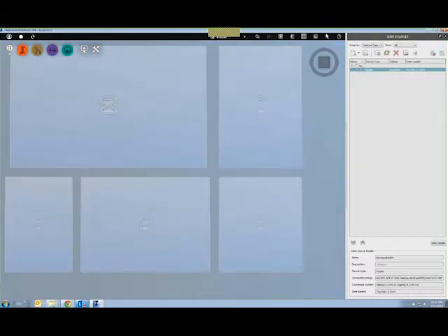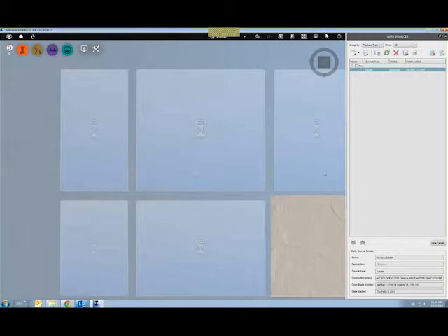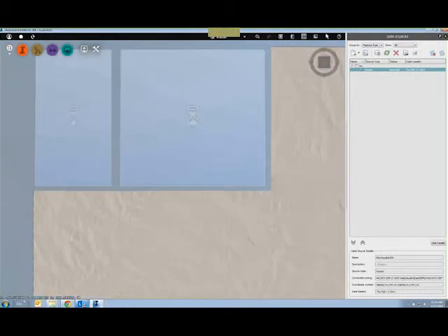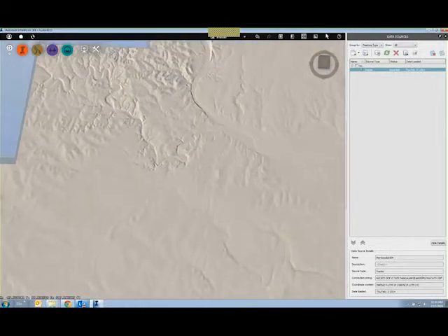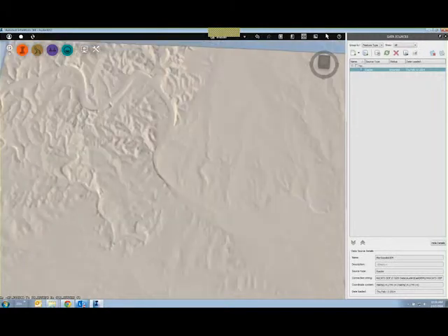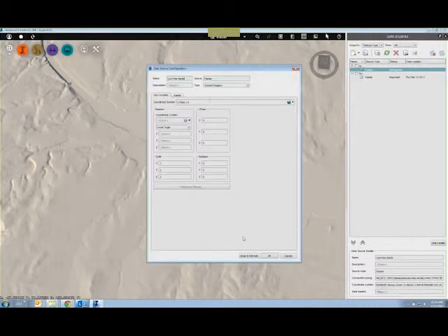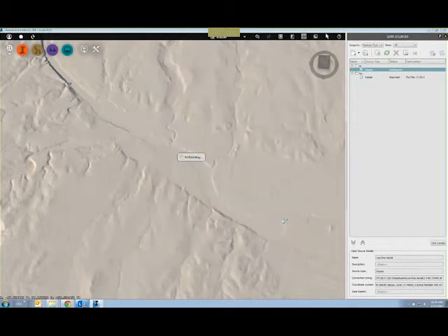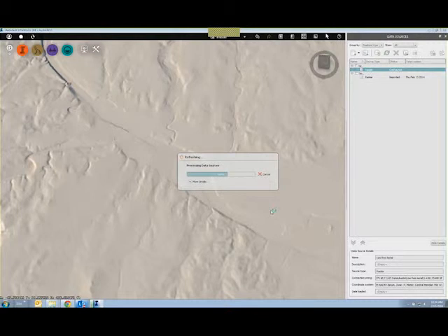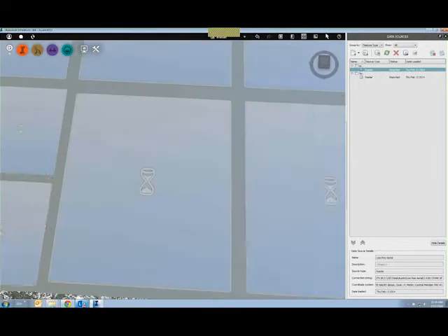Now, what we get when we bring in just the beginning data set is what I call the silly putty surface. This is just a gray, sort of colorless texture, but you can begin to see that we're getting terrain information. And I'll add to that by bringing in some aerial imagery. So I'm going to grab some aerials. Again, these are directly from that national map. Drag and drop. It recognizes, again, that these are ground images. It recognizes the coordinate system. I simply close and refresh, and we will get the downtown Austin aerial data, or aerial imagery, rather.